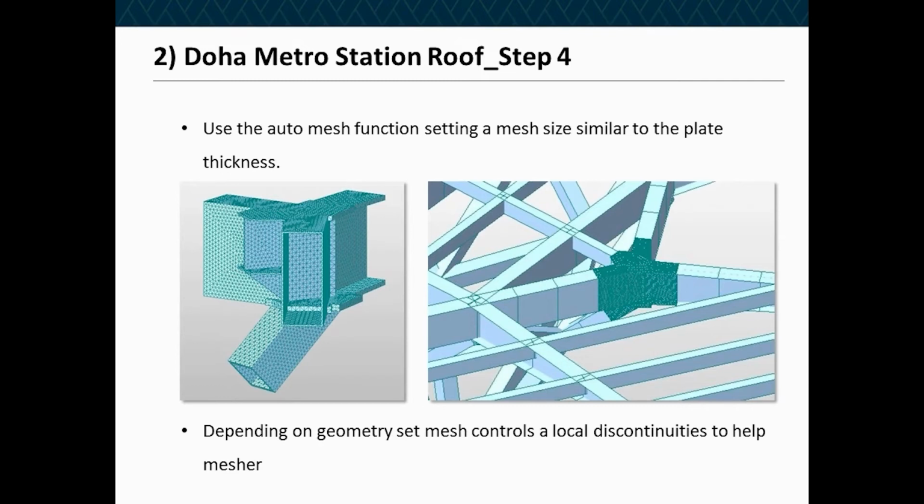So you can't go crazy. But what MIDAS FEA will let you do is control the element size along an edge. It's called mesh size control, and it's a very easy tool to use. Once you've done that, you can then export it using the MCT command within MIDAS and import it back into your MIDAS frame model. Okay?